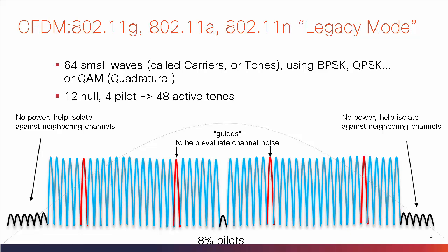What they do is that they do not carry traffic, they send a well-known sequence of signal. It's a pattern that keeps repeating itself over and over again. The reason for those is that there may be some interferences or noise in the channel. By using those pilots, we send a sequence of well-known signals that the receiver is going to read and evaluate.